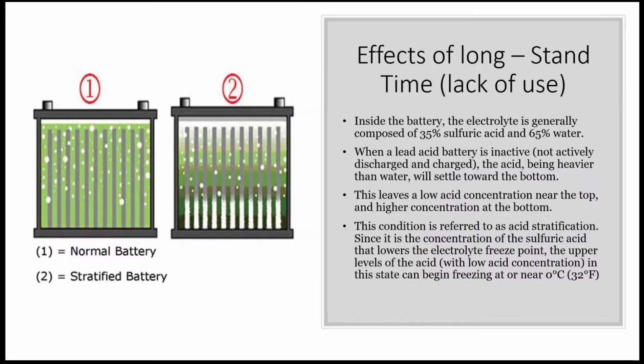Okay, so moving on to our next slide here. The effects of long stand time and lack of use. I'm going to talk about a couple of things here. The inside of the battery and the electrolyte is generally comprised of 35% sulfuric acid and 65% water. That's the solution in an SLI battery, okay? And the SLI batteries with that kind of solution, believe it or not, is pretty toxic. That acid is still pretty toxic.